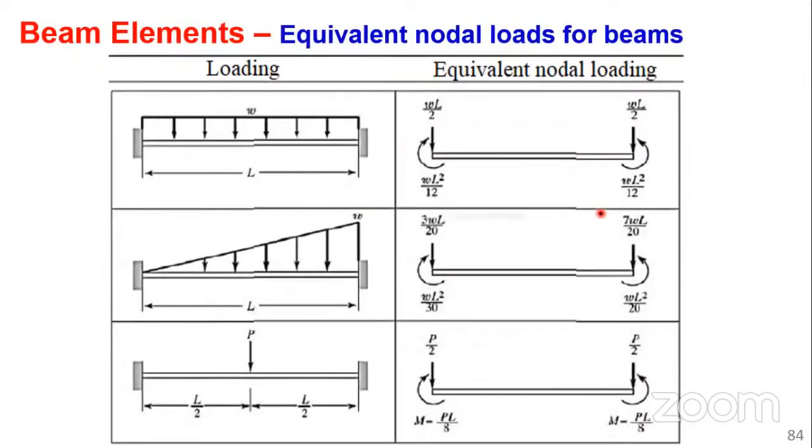So in a beam in a finite element approach, you see these applied loads W over a length L. Of course, resolving the load in terms of the nodal forces is no problem, because it's just WL over 2. You apply it at the support. Of course, the load is applied downwards. That's okay.